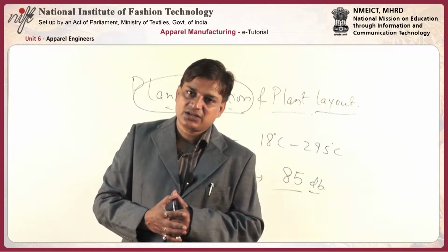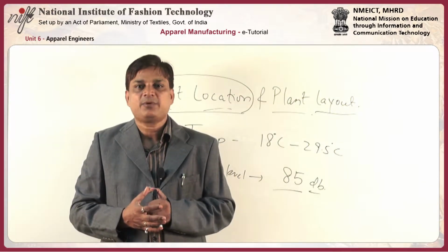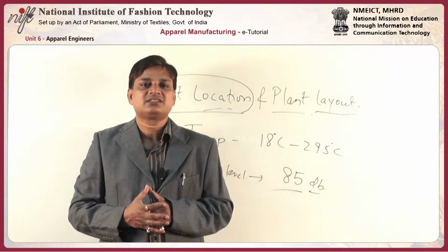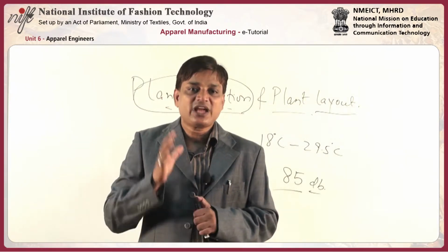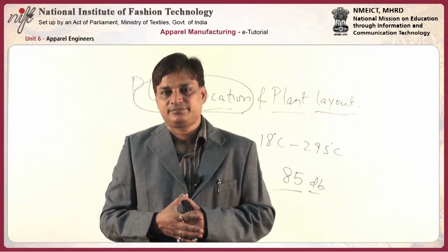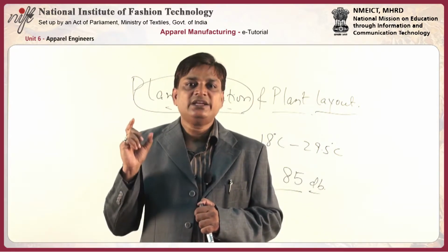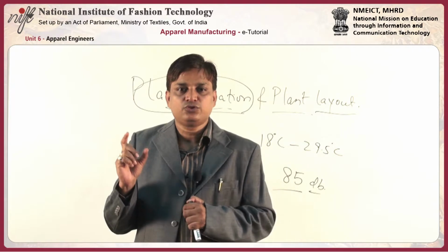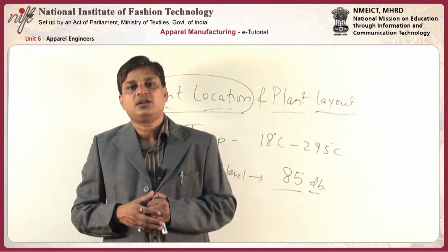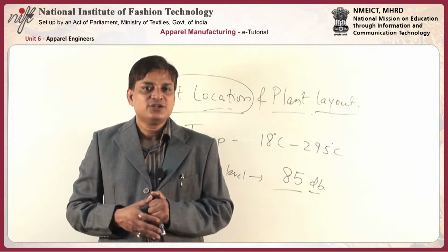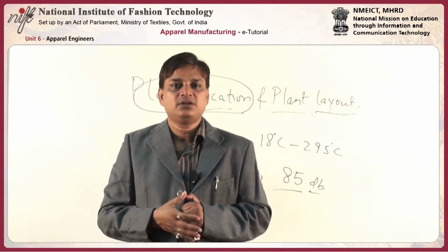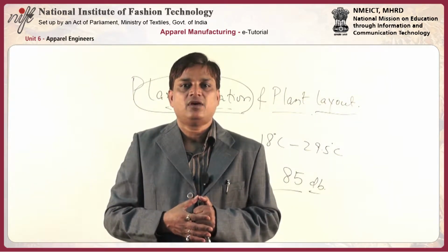The fire extinguisher, appropriate to the type of possible fires in the various areas of the factory, is to be regularly maintained and charged, and the date of last inspection displayed. It is to be mounted on walls and columns throughout the factory so that it is visible and accessible to workers in all areas.